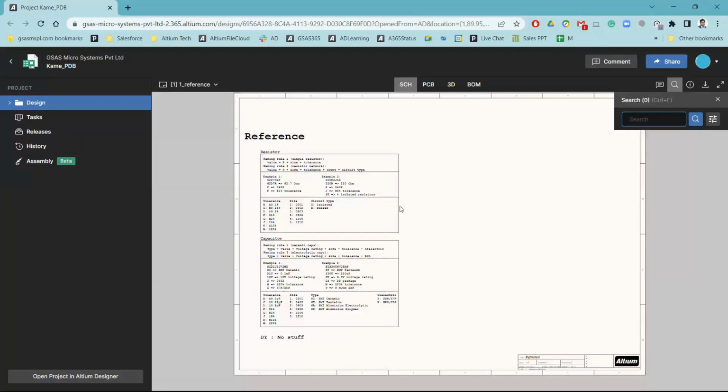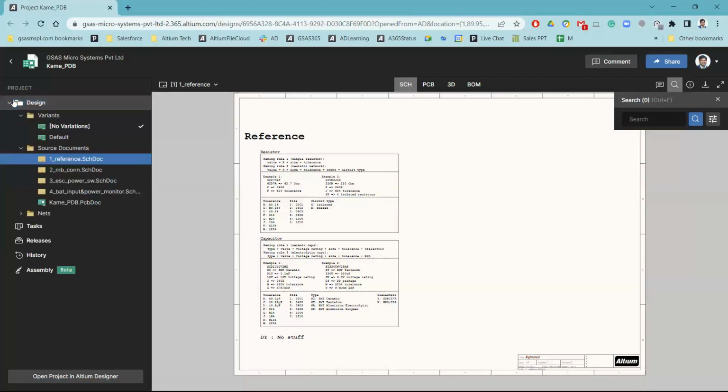As I told you during the presentation, even without having Altium Designer, we can share the Gerber with your fab house. We can review it and share it, which is possible with the help of Altium 365 when we release your data by using the project releaser to Altium 365.